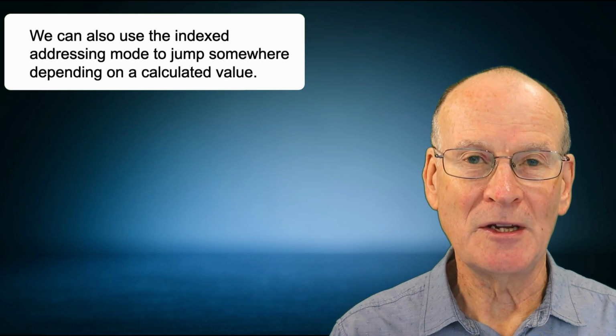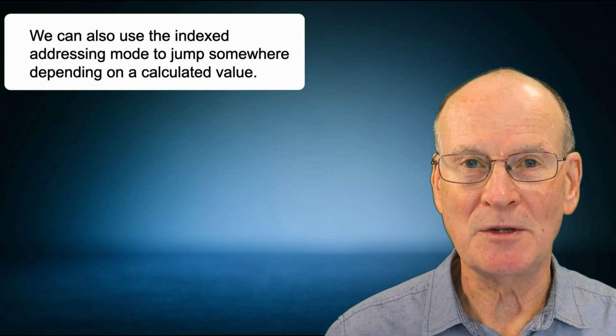This is used for implementing things like case statements or switch statements in high-level languages. The last major operation I want to describe that is in most instruction sets is the ability to do function or sometimes called subroutine calls. This is where we have another piece of code that we want to call. If you know a high-level language, you're very familiar with this. We want to call a function and then return from it when we've finished. And we want to get back to the place just after the call.